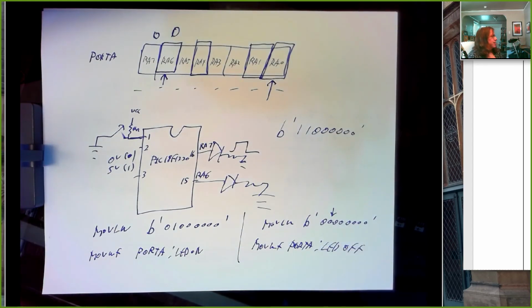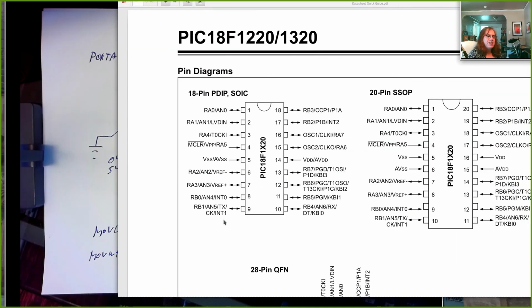All right, so let's talk about I/O. In particular, input versus output. And this is what these TRISA and TRISB registers are about. So again, multiplexing. So 8 pins on port A that we could do input from, 8 pins we could do output on, 8 input and output pins for port B. That's 32 pins so far, just for port A and port B, just for simple digital input output. We've got 6 or 7 analog inputs available, so now we're up to 40 pins, right?